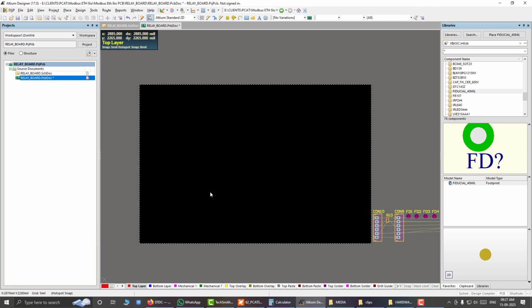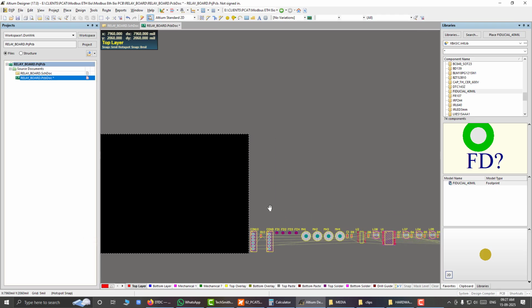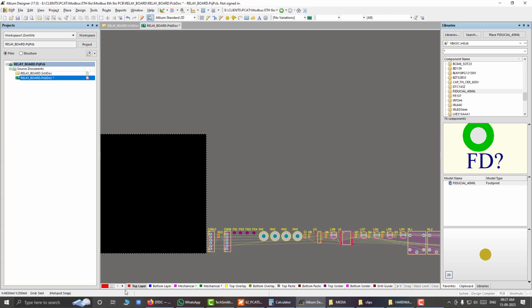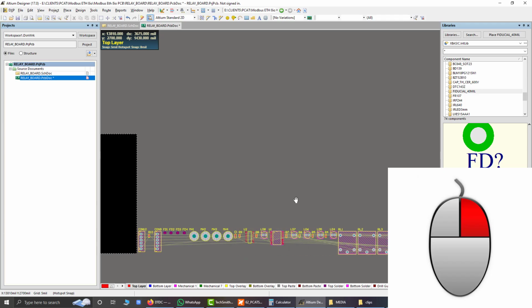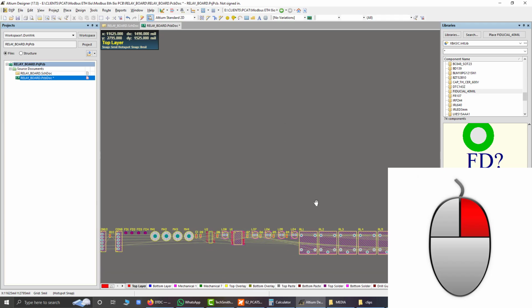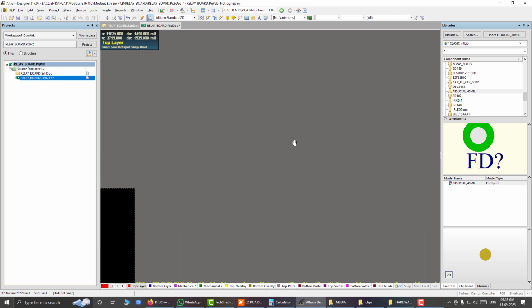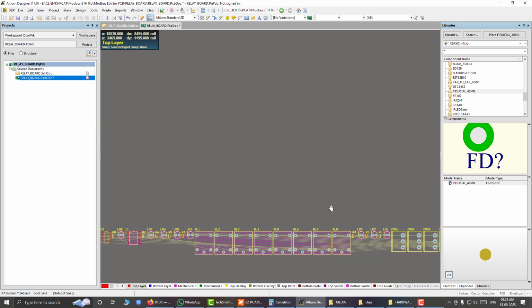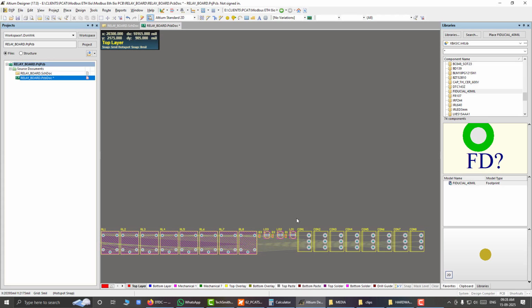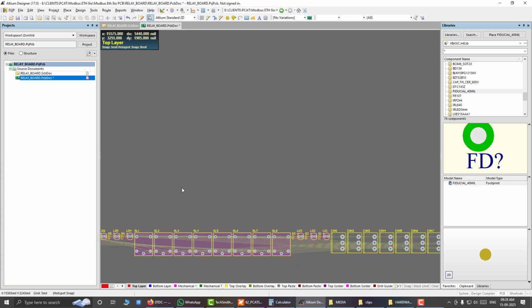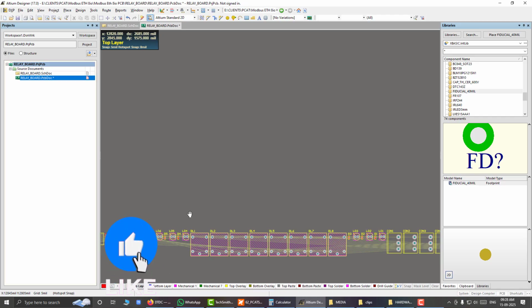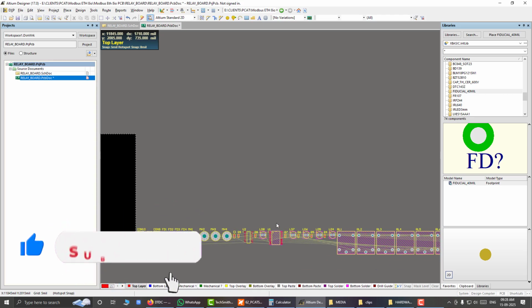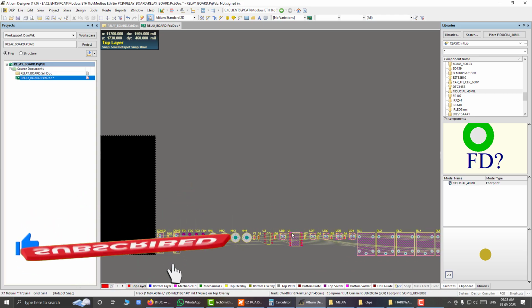And when we move to this PCB view, we will see something like this, all of the components exported here. To pan left and right, click the right mouse button and move your mouse, it will change to a hand like thing. And now you can move both horizontally and vertically like this. Here you can see all the relays, the LEDs, the terminals, screw terminals. Some LEDs are here, some are here. LED 1 2 3 4 5 6. We have our ULN driver, everything we are having here.